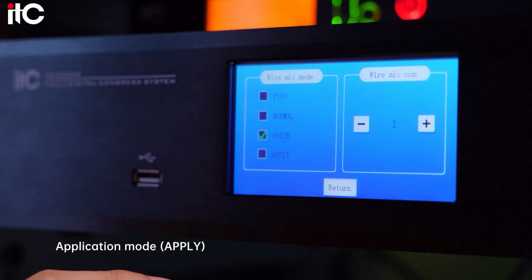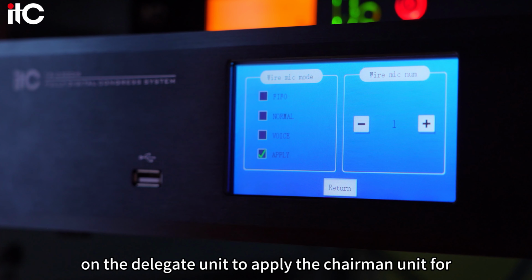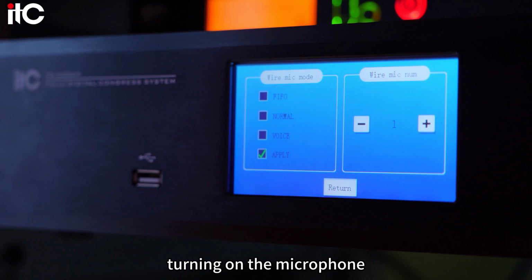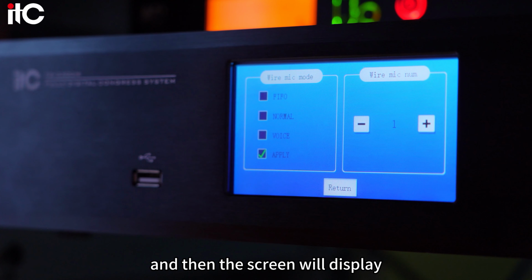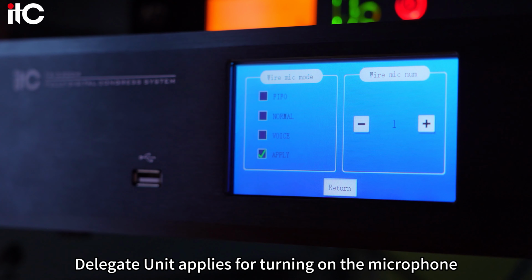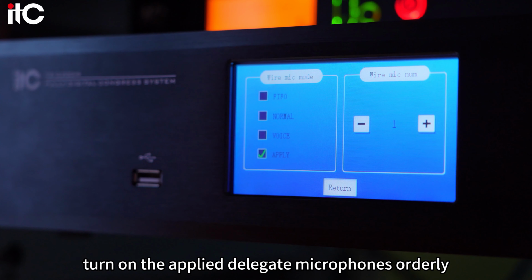And here is the application mode. Application mode for the open delegate unit. Application mechanism. Press the microphone button on the delegate units to apply to the chairman unit for turning on the microphone. At this time, the button number 3 of the chairman unit will flash and then the screen will display delegate unit applies for turning on the microphone. Press number 3 on the chairman unit to agree, and then turn on the applied delegate microphones orderly.